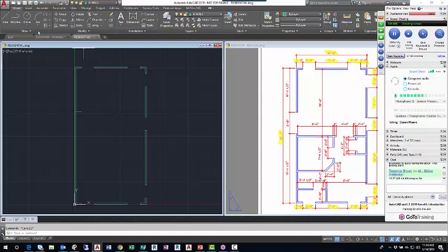I can do a dimension like this. I'll go offset, 10 feet 3, and I want the 7/8. I put a hyphen in here, 3 hyphen 7/8, enter. 10 feet 3 hyphen 7/8. And then as I'm doing the offset, you can see it in my offset window. The value there is 10 feet 3 7/8. Well, you could always do that. You could always use your fraction, but for speed, if you know the decimal equivalent, it might be faster to do it the decimal way.